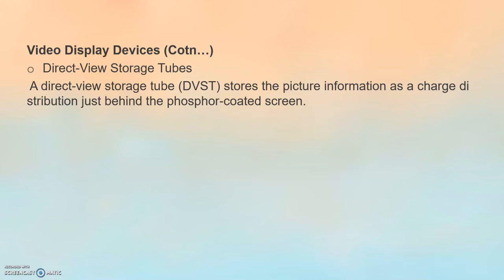Like every other display device, DVST has both advantages and disadvantages compared to the refresh CRT. Let's move on to what are the advantages. Since we already said refreshing is not needed here, very complex pictures can be displayed at very high resolutions without flicker.